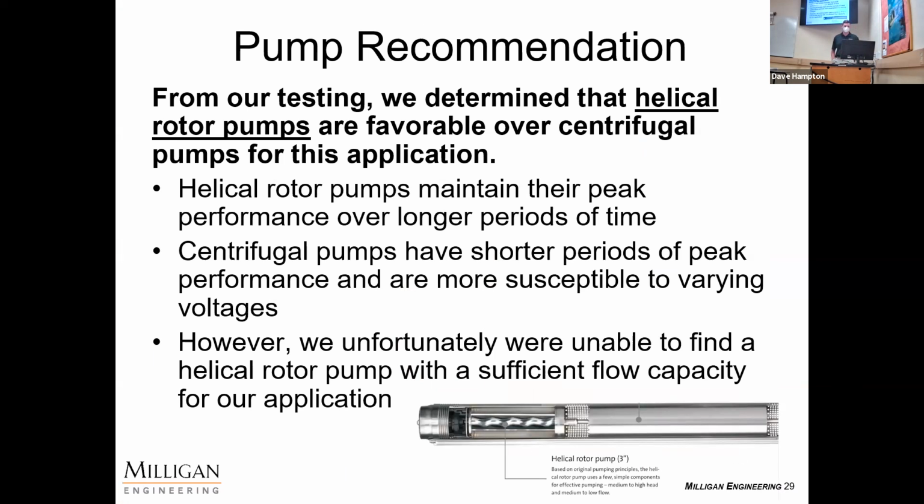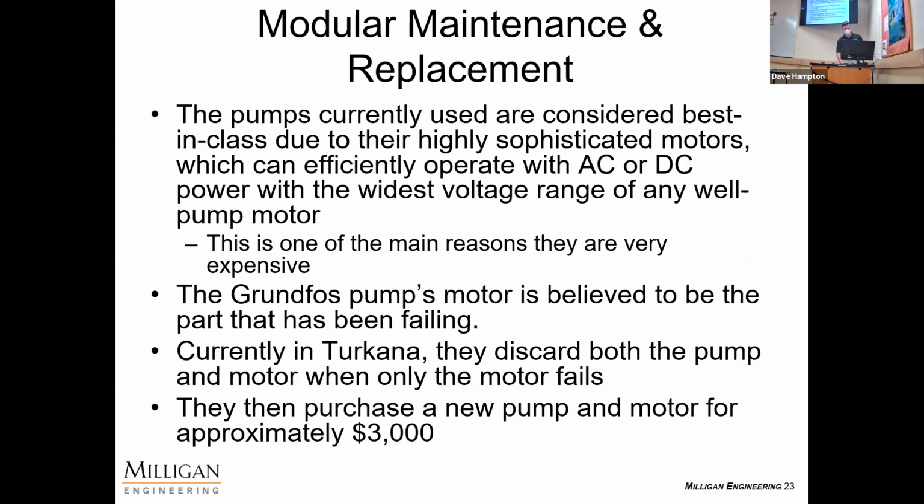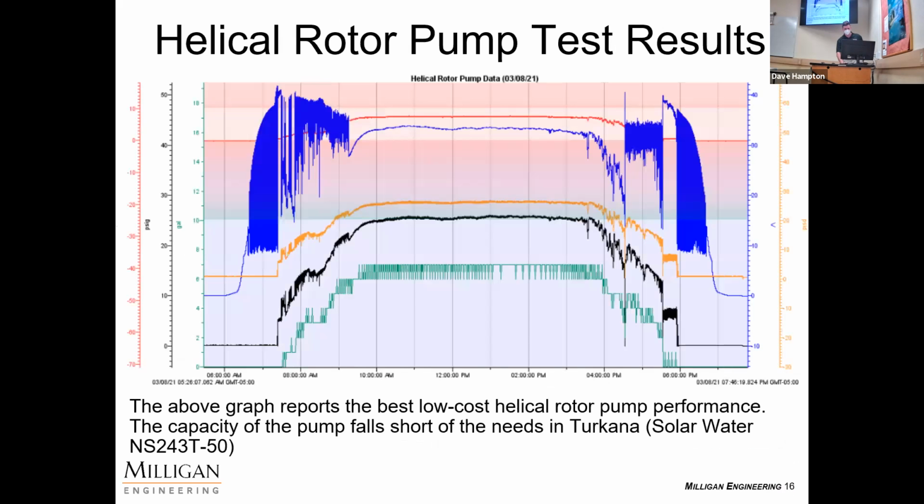The pump that we have here is capable of, I think, about 150 feet of head, or higher than that, just the model that we had over there. When it sees a drop in voltage, it's a power issue. Just being positive displacement, it's always pushing that same volume of water. It's not that it just gets tired. It's just the type of pump. Okay, thank you. Other questions?